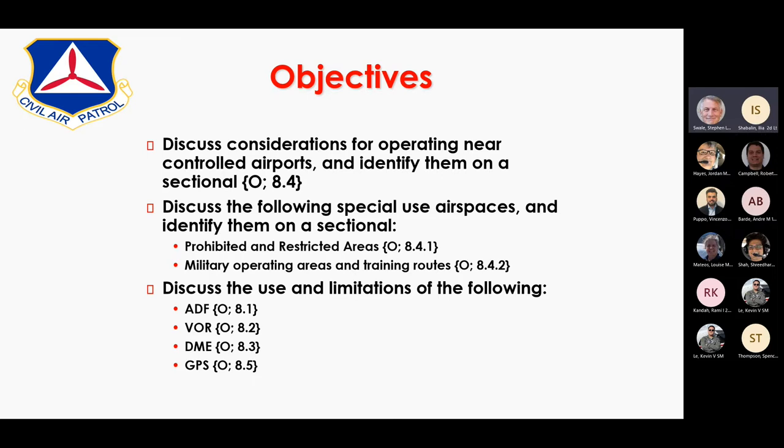We also will discuss special use airspace. There's about a handful of them. Why are they important? They're important because you don't want to have a midair with an airplane that you could have otherwise avoided. And by talking about special use airspace, I hope that it'll remind people that you can call people ahead of time to get coordination, or call up approach control or center and get flight following from them to guide you through these special use airspaces as appropriate.